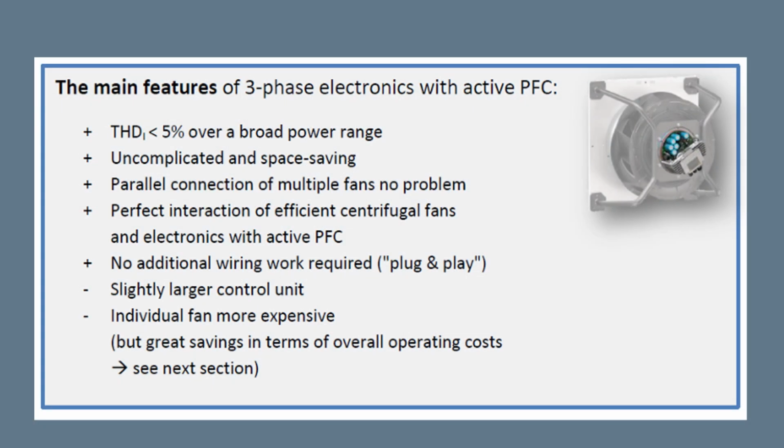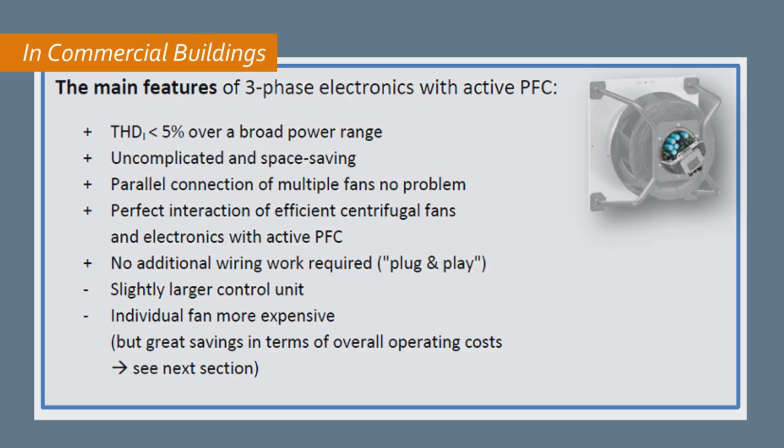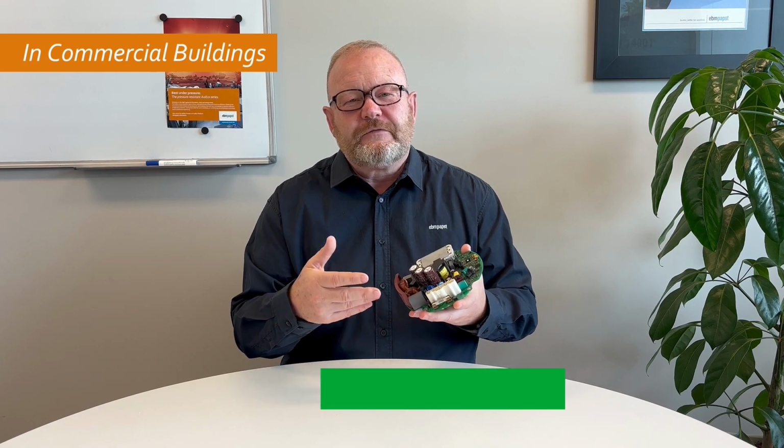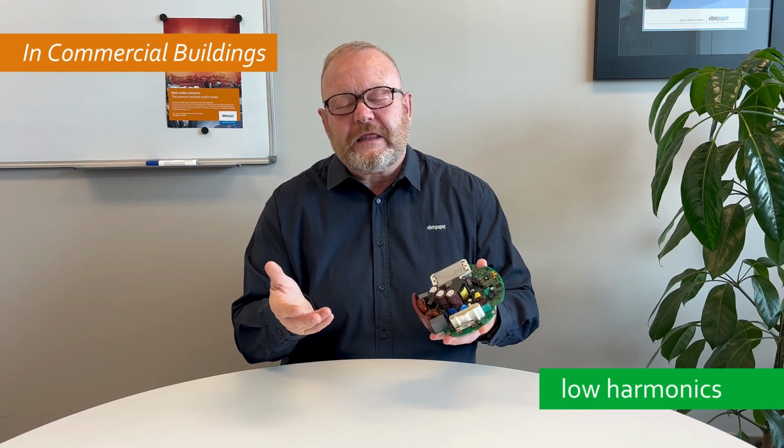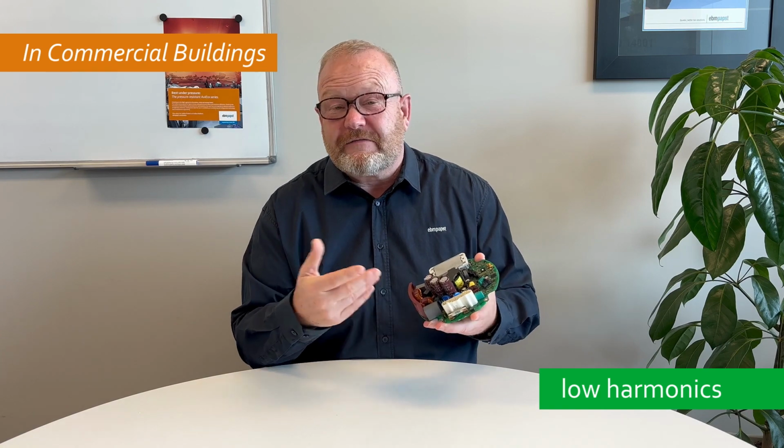So what happens and why? What's the effects of this power factor correction? The main features of a three-phase EC plug fan are shown here in this diagram. So effectively what we're doing is correcting the power systems and making it smoother inside the system. In a lot of buildings, for instance, in hospitals or data centers, there's a power system inside the building, so a combined heat and power system, for instance. And these combined heat and power systems need a good, smooth electrical supply inside the building, such that the harmonics are low. Typically they'd ask for a total harmonic distortion on the voltage line of less than 5%. And by using active power factor correction systems, you can get the harmonic distortion low.